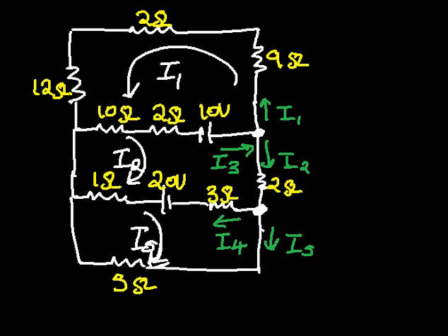Now let's start with the analysis in terms of the formulas. Let's apply the voltage law in each loop. Let's start with loop 1. What is the current flow in loop 1? We have it as I1. Of course, it's not always that in loop 1 we'll have I1. Sometimes you can have I2. It depends on how you have labeled the current itself, but it doesn't matter.